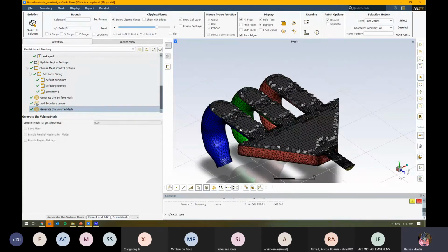All right, so I think those are the main things that I wanted to show you guys. Hopefully you've seen a bit of Ansys meshing and Fluent meshing, some workflows and some geometries that we're working with. In both, we've got geometries that we can bring in and play around with the sizings. We've got global and local sizings that we can add. In Fluent meshing, we've got the additional capabilities of working with different mesh topologies, whether it be polyhex core or hex core, and we can also generate polyhedral elements inside Fluent.